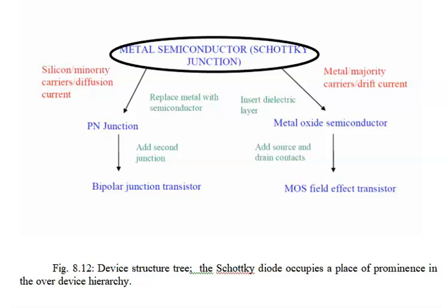The first chapter is equilibrium, which we'll start today for the MS, the metal semiconductor, then non-equilibrium, where we put in voltages, and the third chapter is where we do some worked problems. The equilibrium part means that it's just sitting there as a structure. Nothing's flowing. The Fermi level is straight and horizontal.